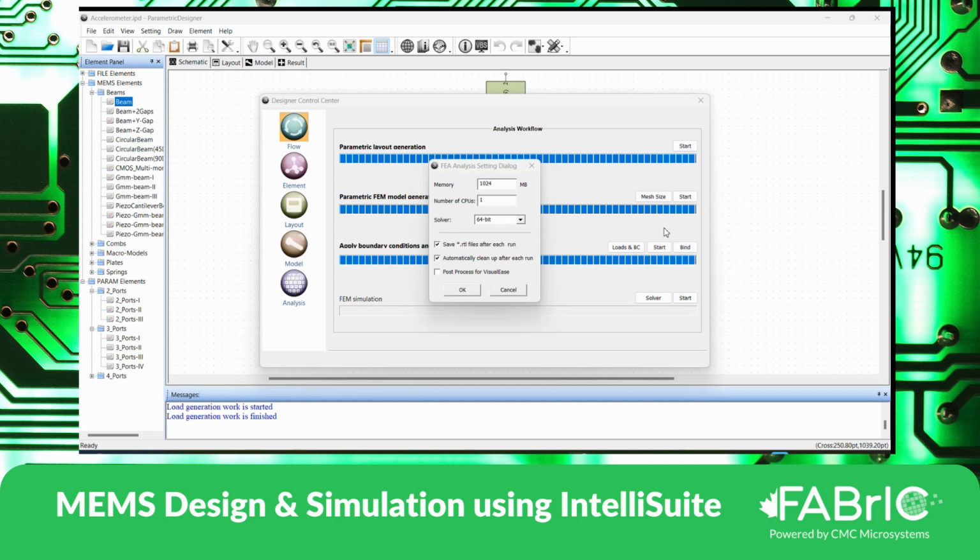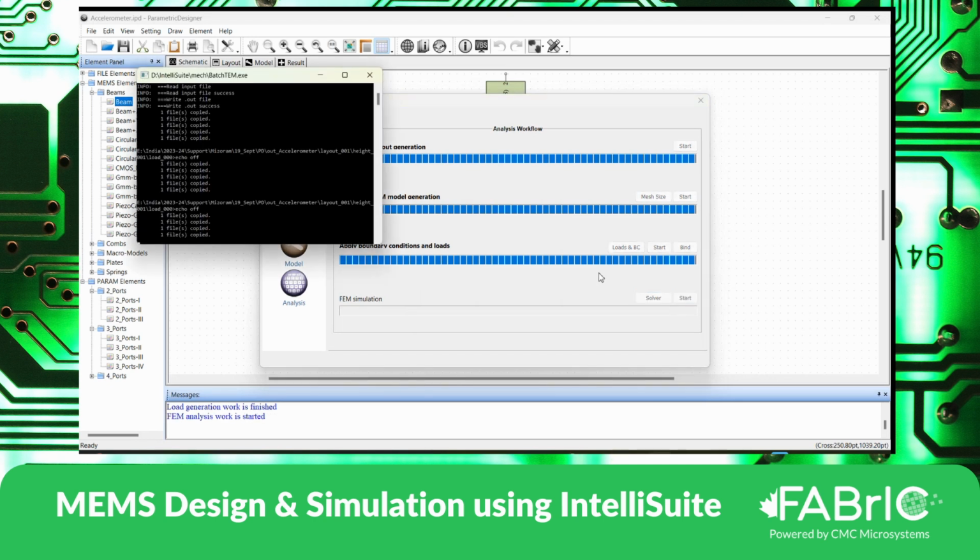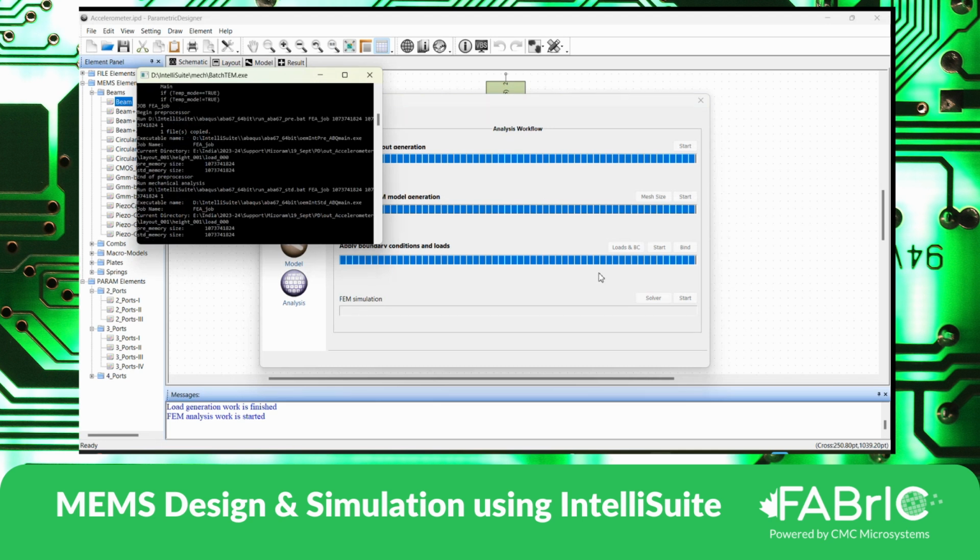So now what the software does is, for the accelerometer base design, for the length of 100 micrometer to 200 micrometer, there will be an increase in the beam length on all four sides together. And at every 10 increment, it calculates the natural frequency and then finally plots the graph. So we take a 64-bit solver, then we click OK, then we start. So now it has to run natural frequency analysis for 10 different geometries.